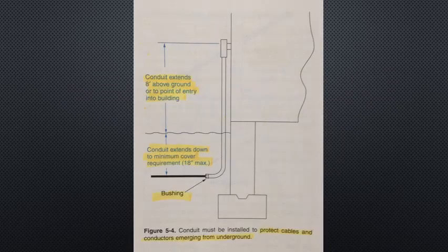See Figure 5-4 for an example of this. At the point where the underground conductors emerge from a raceway, the raceway should be fitted with a bushing or sealed. Regardless of the methods of wiring used, all underground installations must be grounded and bonded as required by the Code. Refer to Chapter 10 of this text and Article 250, Grounding, of the Code.